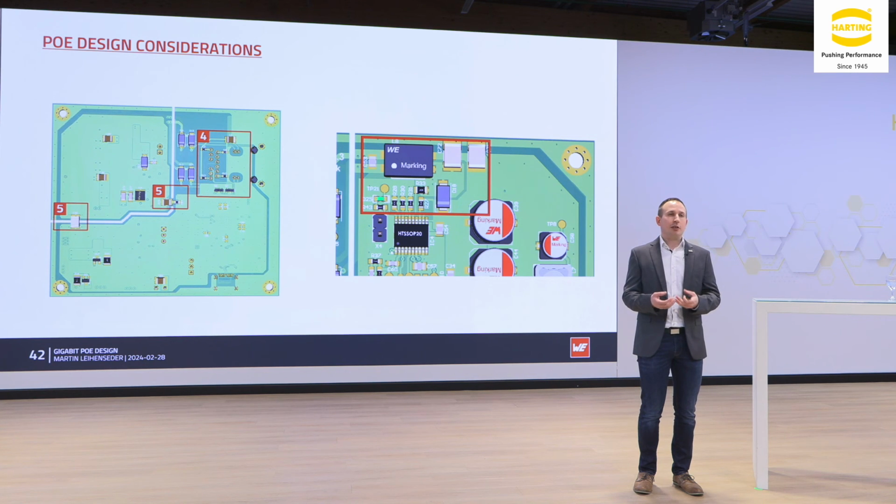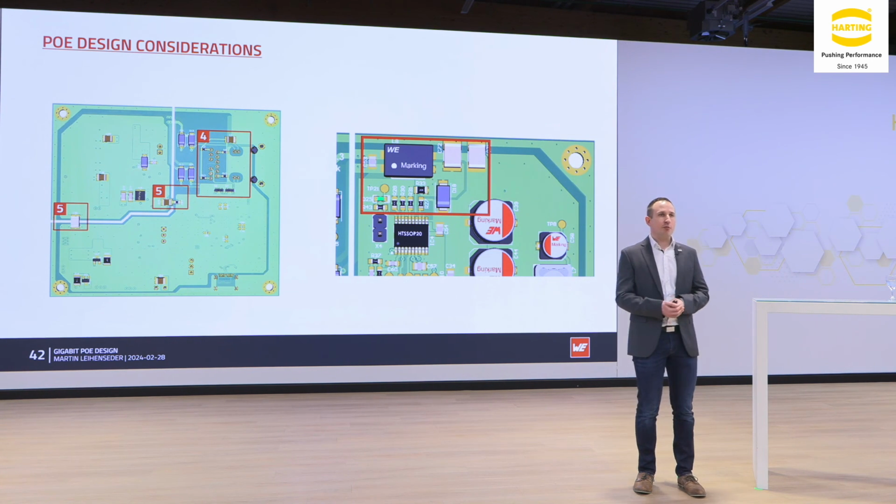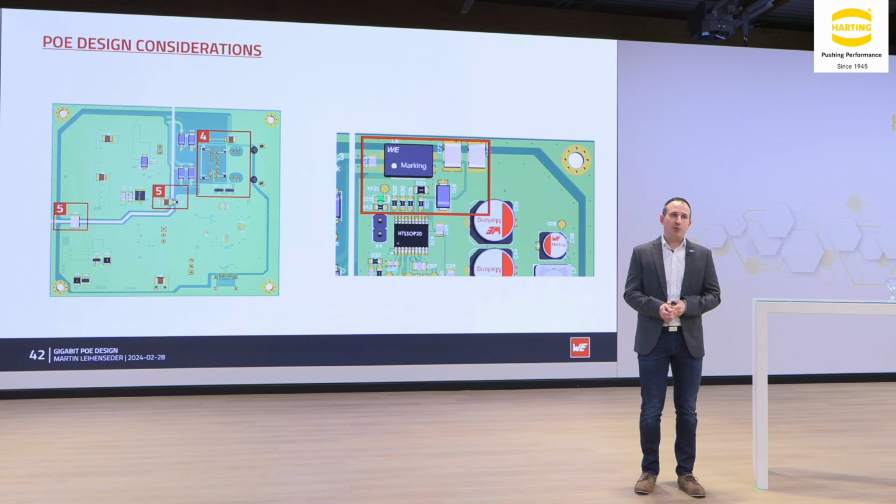So we need big wires. And also the inductance needs to be high so that the common mode choke is very broadband. And then we have big capacitors inside. These are the big capacitors, for the common mode signals, or to reduce common mode signals, and small capacitors. These are not marked here. This is for differential signals.